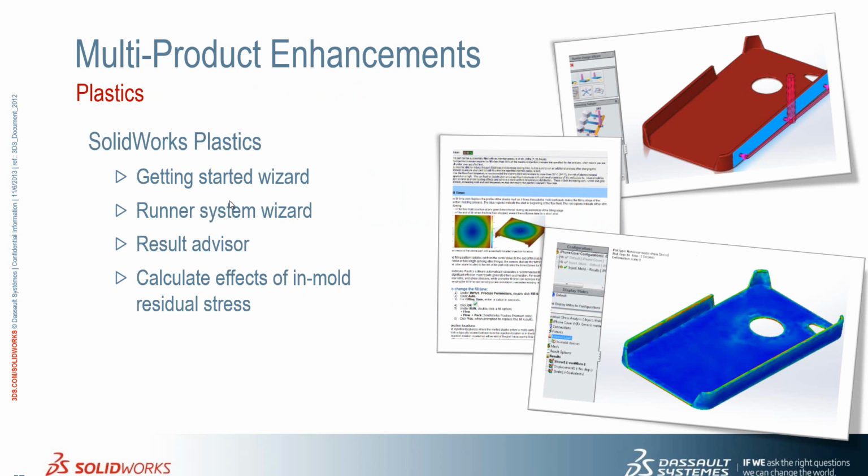Okay, so in summary, we've seen the new Getting Started wizard, the ability to use a runner design system wizard, the results advisor have seen a nice overhaul, and we can also calculate the effects of in-mold residual stress and export those to simulation for more accurate displacement results.